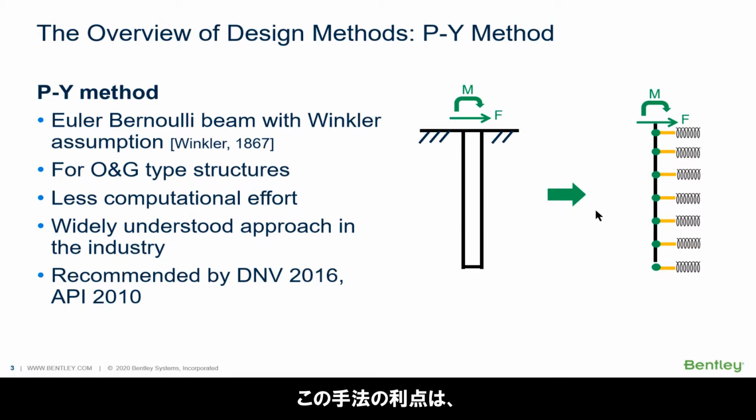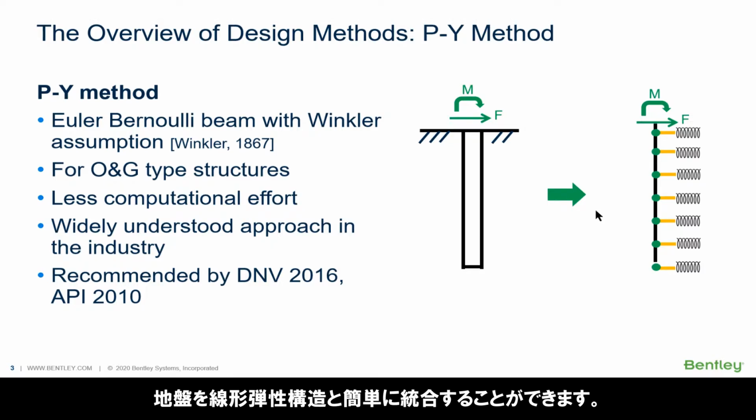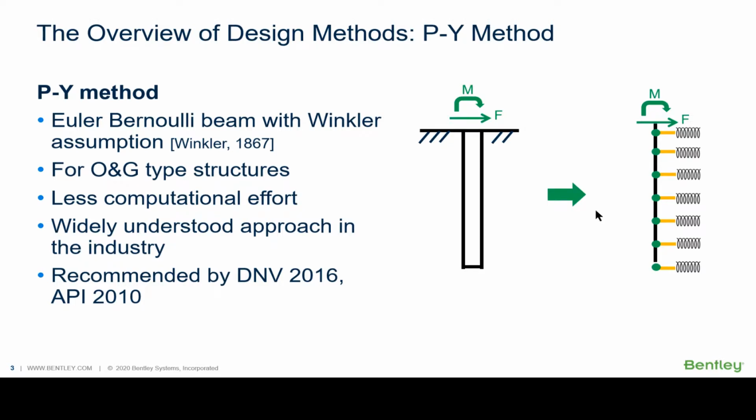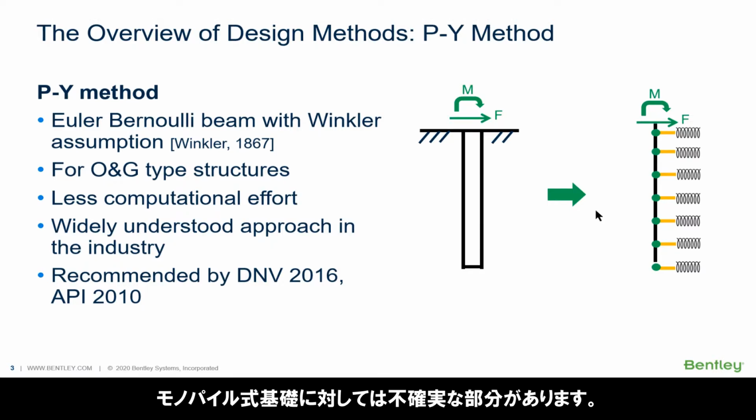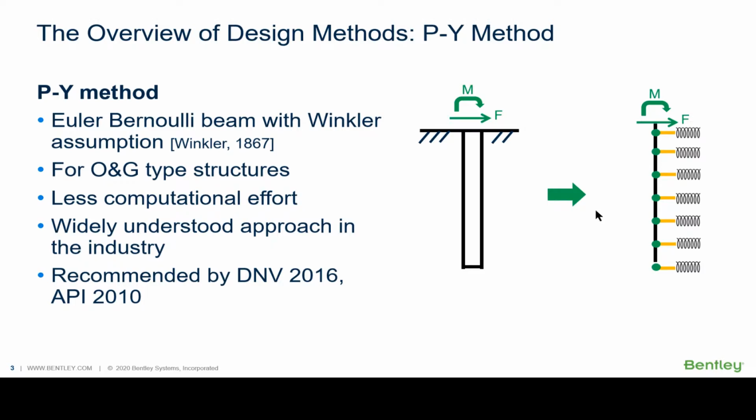The main benefit of this approach is that it needs less computational effort. So the runtime, the analysis time, is relatively very short, and it is also very easy to integrate the foundation with the linear elastic main structures for global structural analysis. This approach works well for slender piles, but it has some limitations or uncertainties for monopile foundations. Let's take a look at this in detail on the next page.